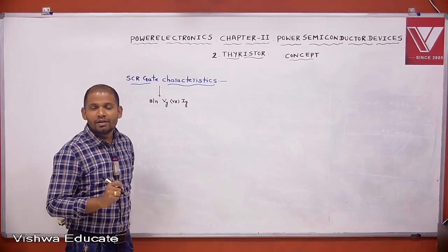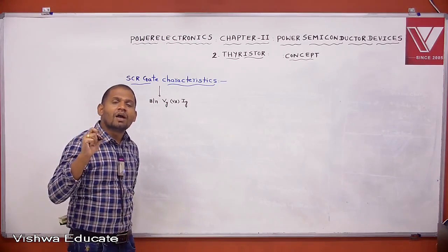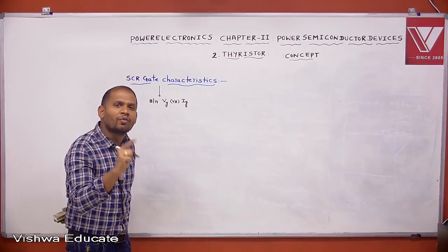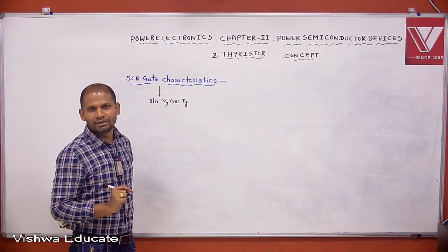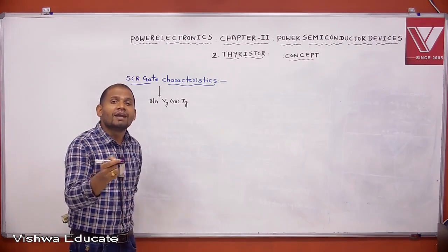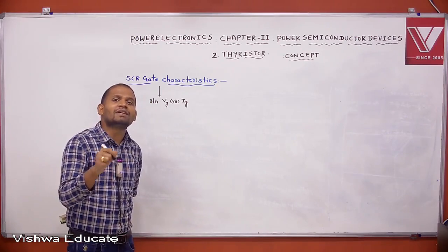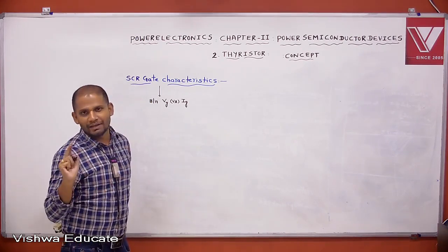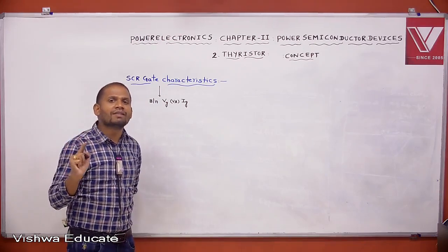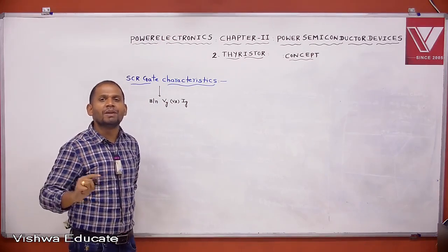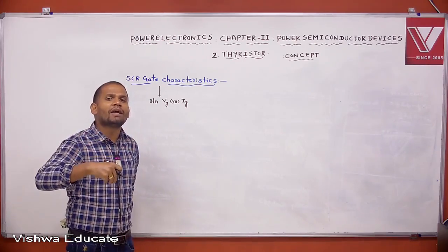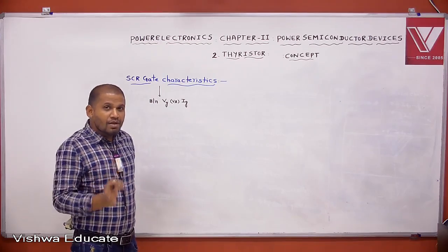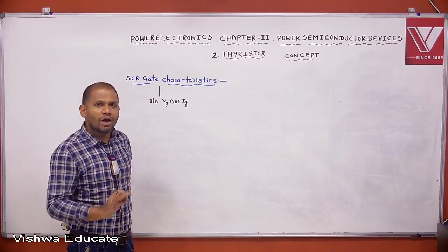That's why for a given thyristor, we need to know at what voltage and at what current the gate must be supplied. To design the gate voltage and gate current, it is required to draw the gate characteristics. That is the significance. Simply, to find the operating point of the thyristor gate terminal, we draw the gate characteristics. How to find that operating point, I will also explain.